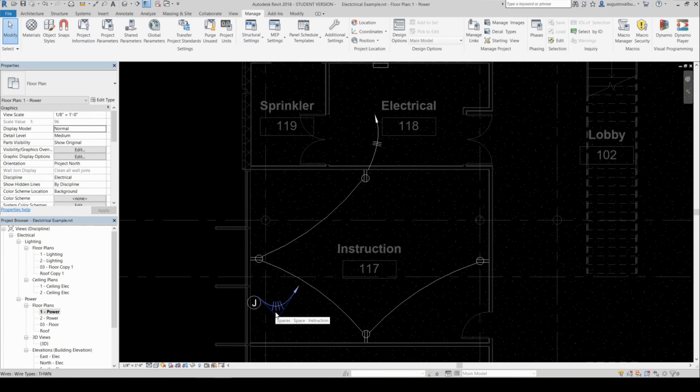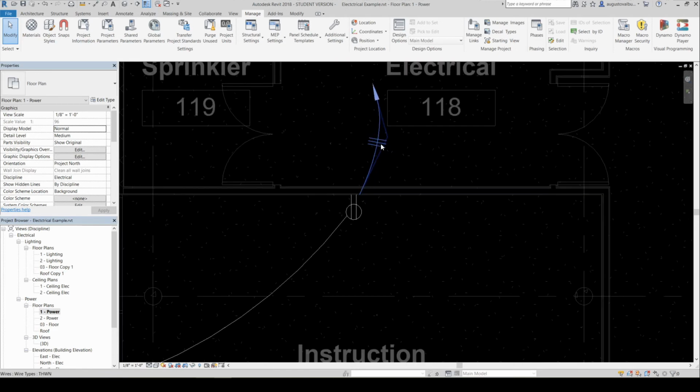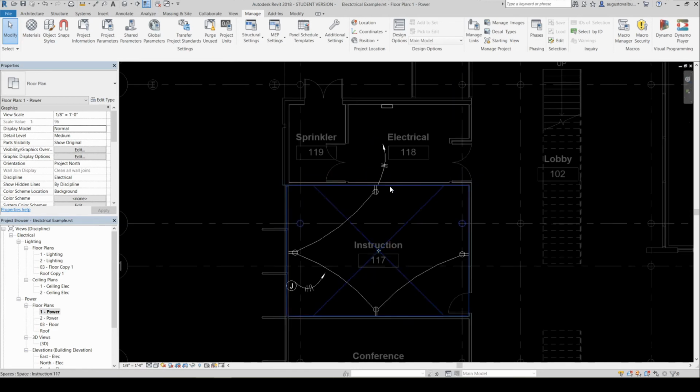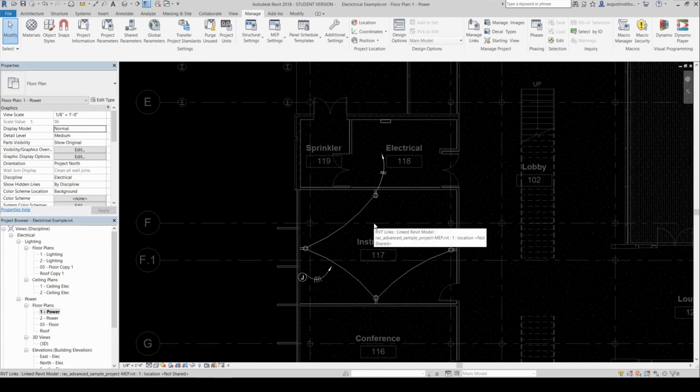And the difference is that this is a 2-pole, and you can see how Revit recognizes that and adds 2 lines on the wire. Why is that? Because it's 2 hot wires, the neutral wire plus the ground. And the same here, 1 hot wire, 1 neutral, 1 ground. This is convention on the electrical design. You can leave it or take it from the option I showed you before. Now we have created the wire.